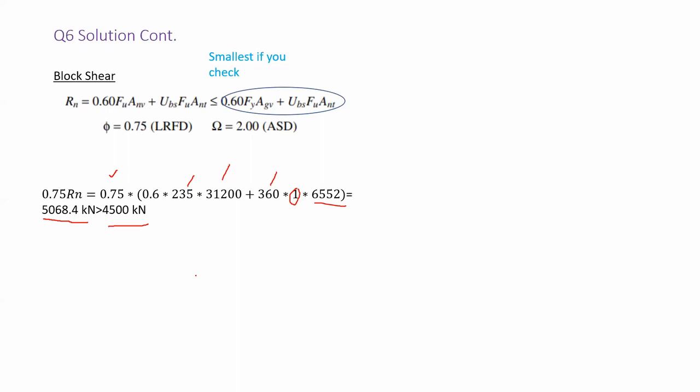So all of these. And if you compared, let's say, HEM 300 and HEM 350, both of them satisfy your requirements. So the safety is good. We have safety satisfied. Now we have to satisfy economy. When you want to satisfy that, you have to consider the lightest weight member in between these two.